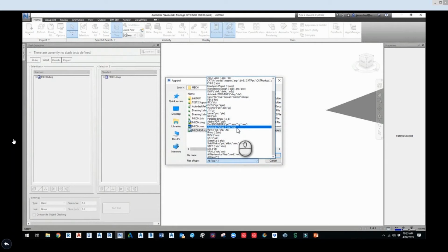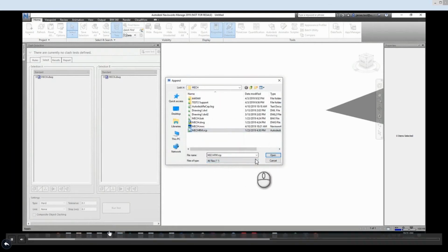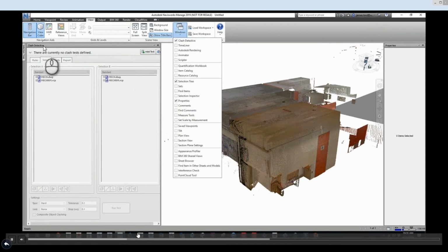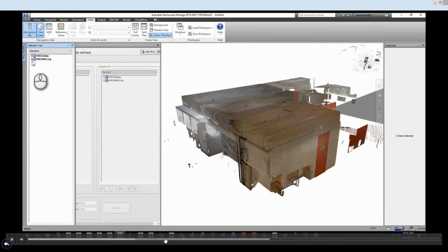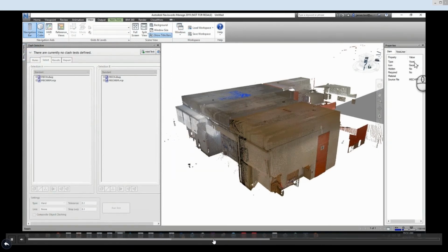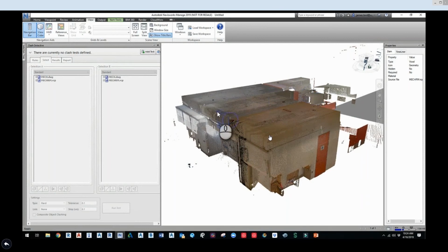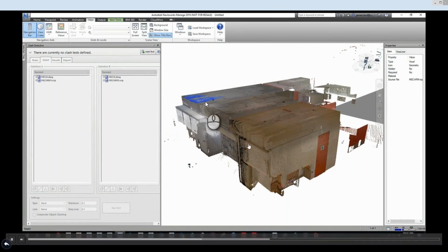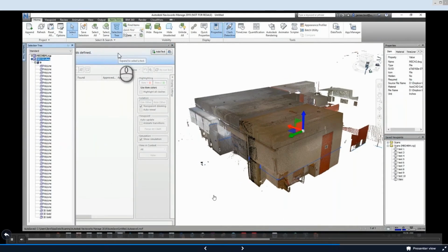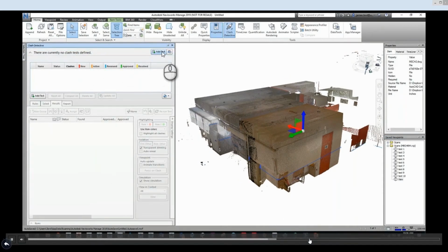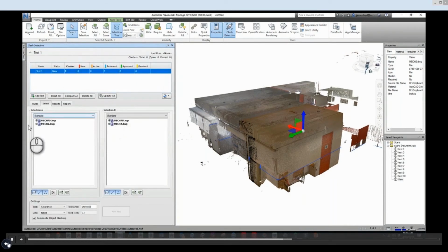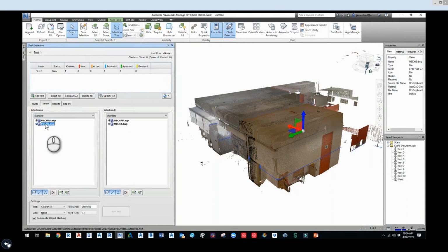If you guys want these files too, I can give you the files as well. Basically, this will set up the collision between the two different types. The only thing that it does is it will automatically make things called voxels. A voxel is just kind of like an area of a point cloud, and there's no way you can specify what is a voxel. It's just what Navisworks makes. But ultimately, you can run the clash detection and get your test results, and then see what's colliding with what, and go through the clash list.